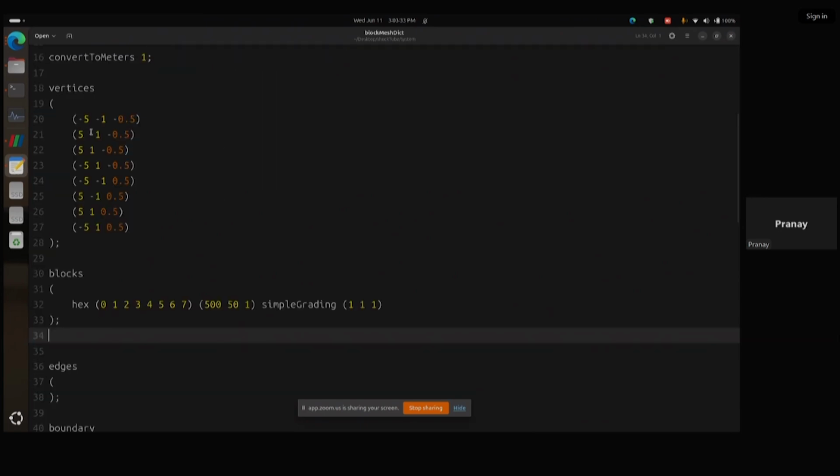So, as this is a copied tutorial, in the tutorial you would have found the case to be extending in the z direction. This represents x, y, and the z direction. In the original case, it was 1 meter. Okay, I have modified it to 0.5. Anyways, we are not interested in the z direction, so you can model it anyhow, whatsoever the length is. It extends from -5 to +5 as discussed earlier, and the width extends from -1 to +1.